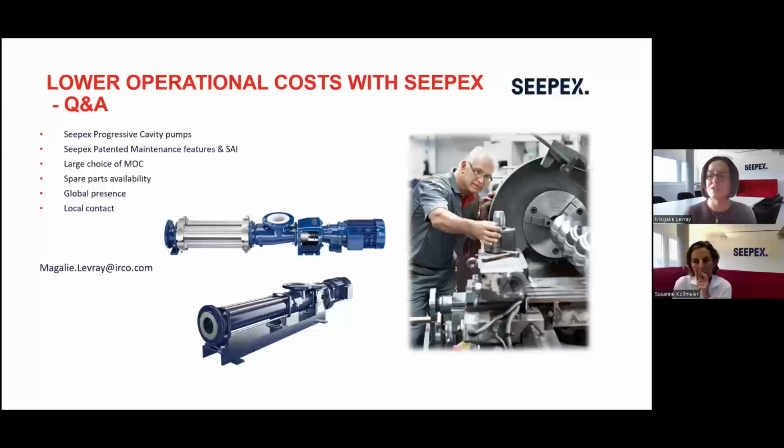So in dosing applications, I would say that is a limitation, definitely. We know as well that they have pulsating flow rates. So whenever we have a large distance, that means we need to install pulsation dampeners. So that comes at an extra cost.